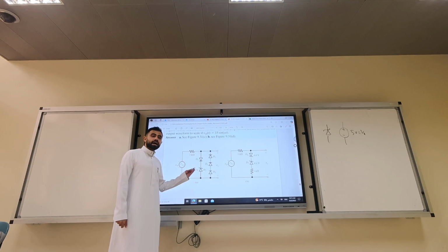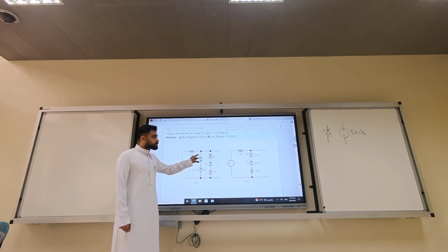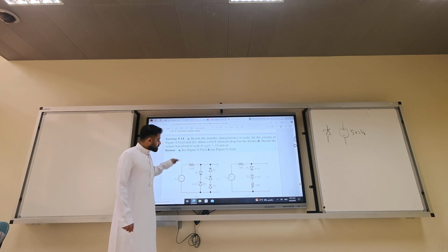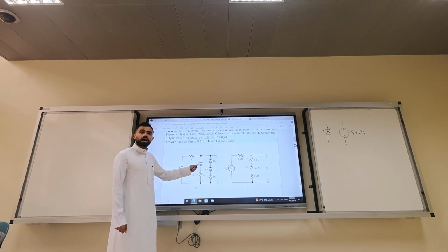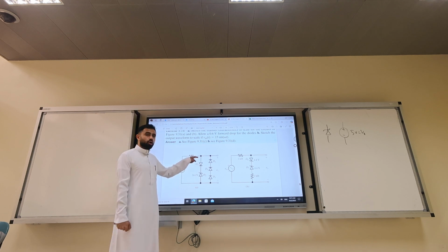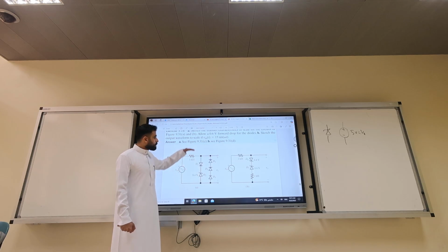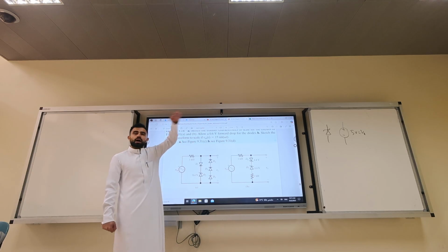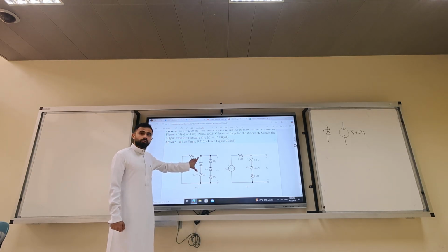What did I tell you if we connect a Zener diode with another diode? We want it to operate as a battery of 9.4 volts. So this is 9.4, this is assumed to be 0.6. So 9.4 plus 0.6 is 10. So I need 10 volts positive to operate this in the forward bias and this in the reverse breakdown. So anything above 10 volts, we will clip our voltage to 10. So what's our upper cap? 10 volts.